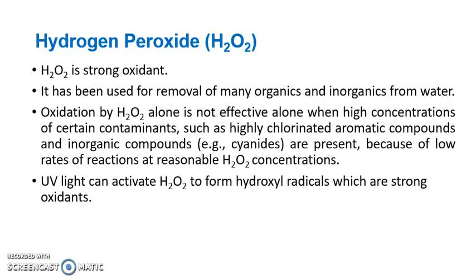Hydrogen peroxide, in many of those advanced oxidation processes, we are applying the hydrogen peroxide. It is a very strong oxidant. It was used before for removal of many organics and inorganics from water. But if you want to apply only hydrogen peroxide, it's not that effective compared to the condition that we are applying hydrogen peroxide in combination with ozone or UV light.